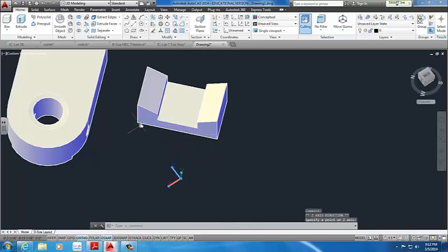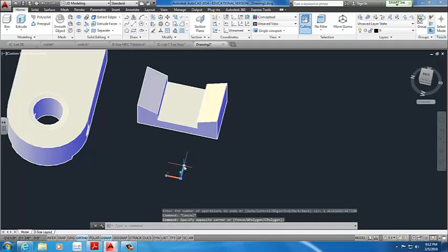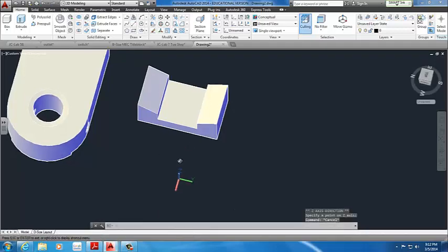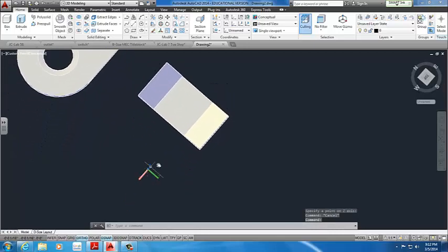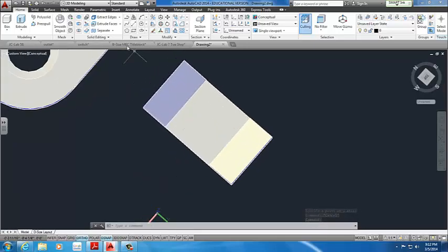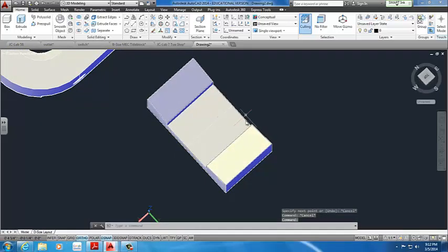It's kind of got an angle, so I have to undo that. There we go. So if I look at the top, I have the X and Y coordinates looking at me. I draw a reference line from midpoint to midpoint to give me the center of this part, and this is where we can start creating these circles, the cutouts.